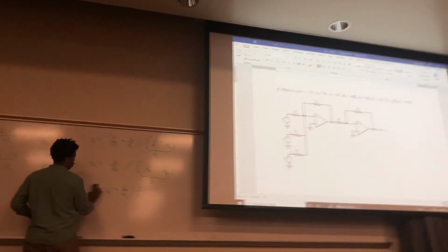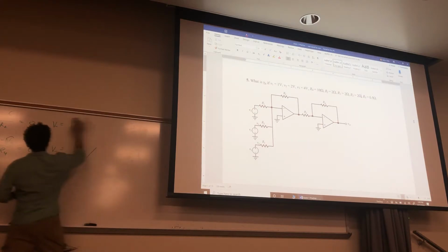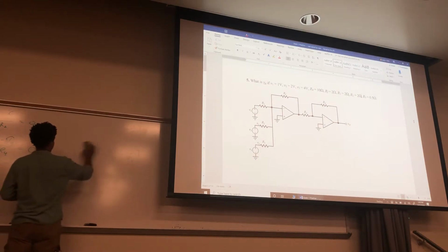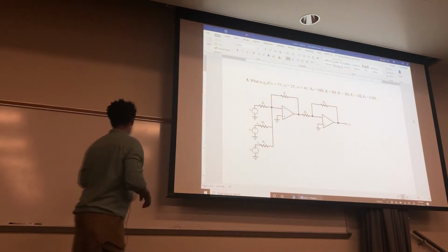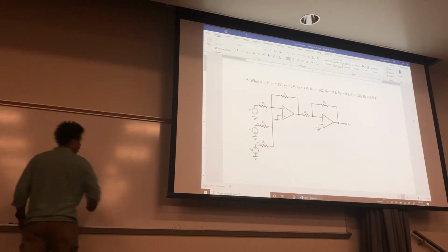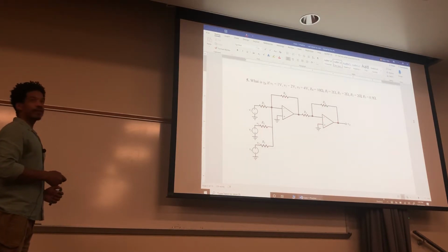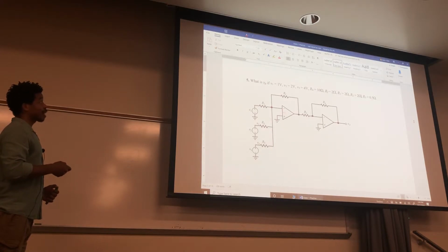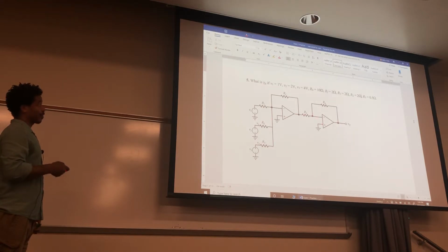So if it has an R4 and R4, what kind of inverter is it? It's just like a unity inverter. It's like multiplying it by -1, right? So in that case, why do you think this is there? Do you think that's really necessary? Yeah, because this is a summer, but it's also an inverter. So here's an inverter to invert the inverter.